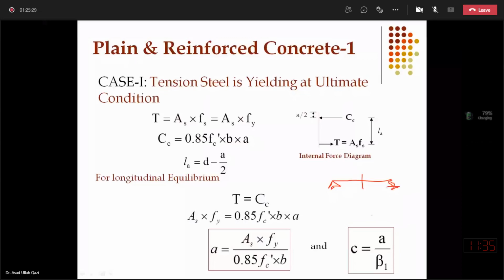The midsection is maximally stressed, and at that stage the midsection may have a strain diagram like this, where the top fiber approached 0.003, crushing concrete, and steel at that stage, in this case 1, as we said, will be at epsilon y.